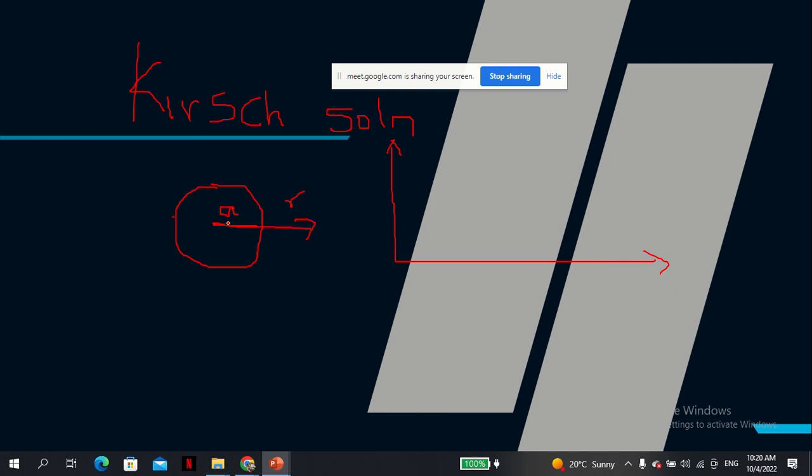So let's say some radius which is above the hole. If you draw a curve of r over a, this hole has some forces, let's say from here. It's easier to indicate this way. So there are stresses in this direction called sigma r, and similarly, there are stresses tangential to the hole called sigma theta.